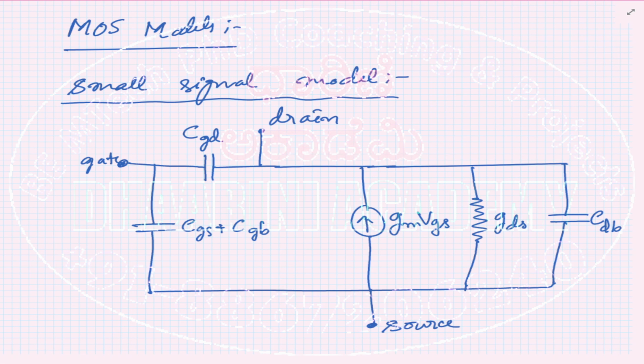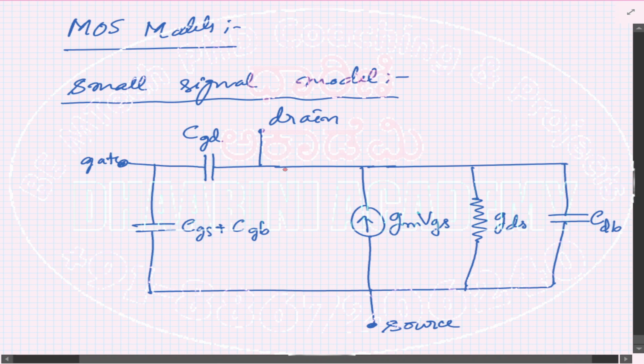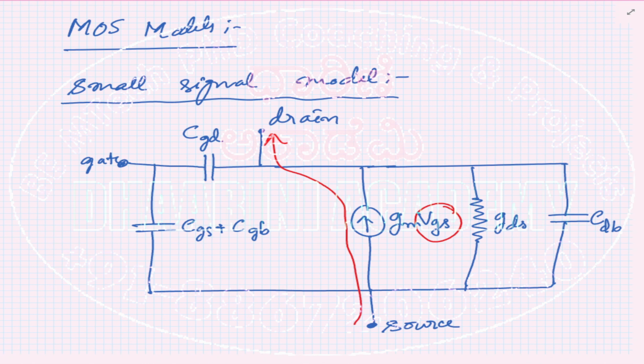And in which direction do you have current flow? Drain to source. When current flows from drain to source, what is the direction of flow of electric charge? It's source to drain, see the direction. And that current depends on what voltage? It is VGS. See, the current is dependent on that. So everything is modeled right here clearly. That's why this is called a model. A transistor can be modeled in this fashion. Very straightforward. I hope you are fine with this concept.